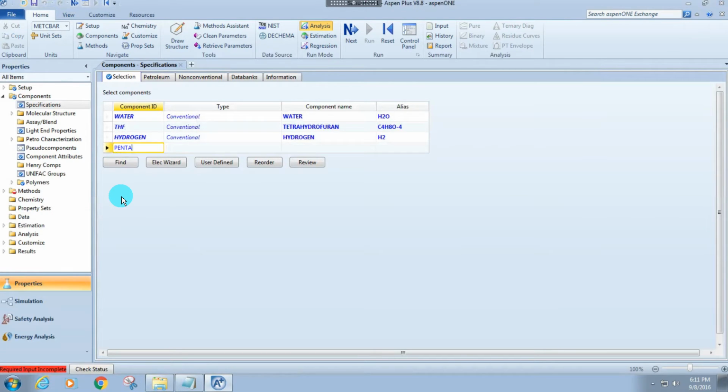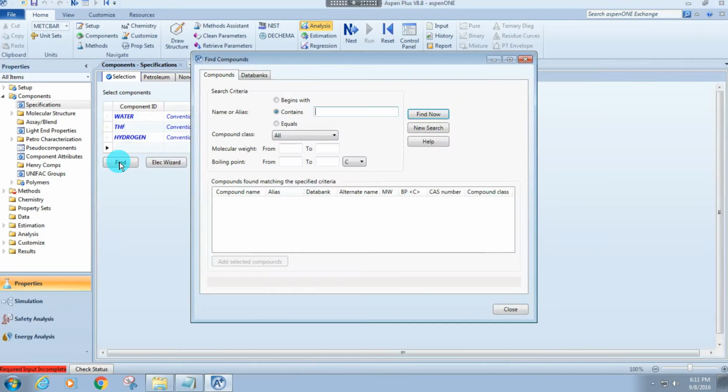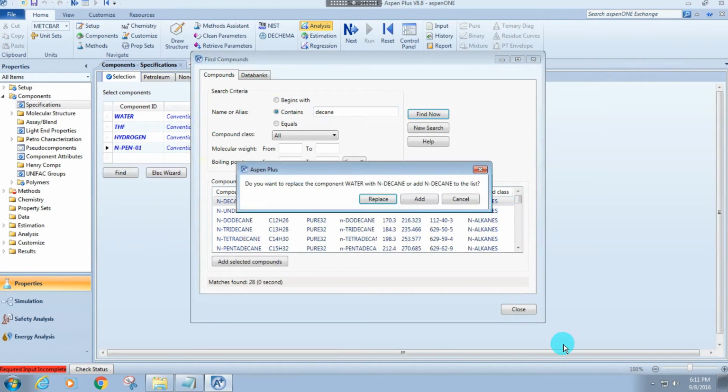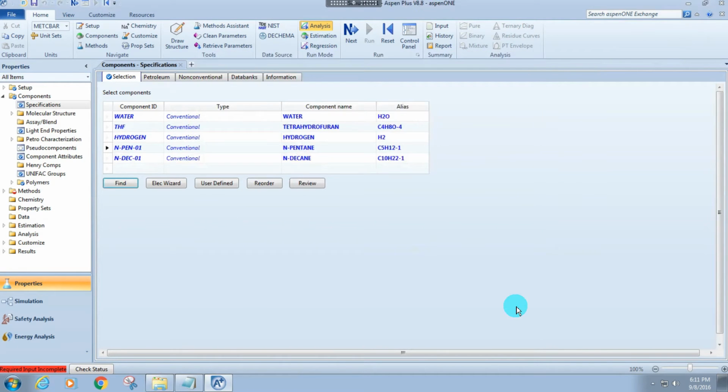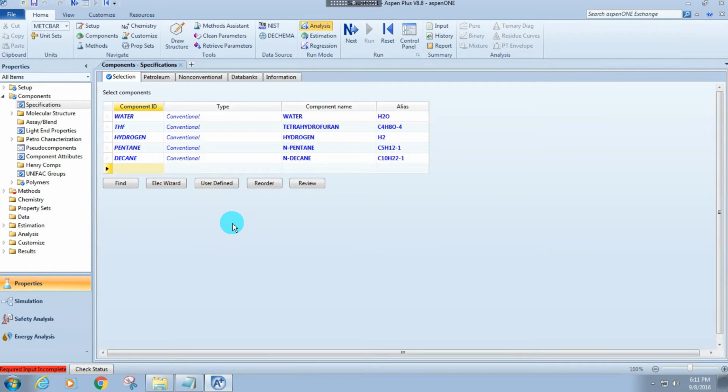And we will use pentane, and I can't believe it doesn't recognize that. Yeah. Pentane and decane for a very quick example later on. And you can also just put the empirical molecular formula into that Finder box and search from there too. So you don't have to actually know the name, just kind of know C2H6 or something like that. Yeah. So up to this point, everyone's familiar with. We finished inputting the components.